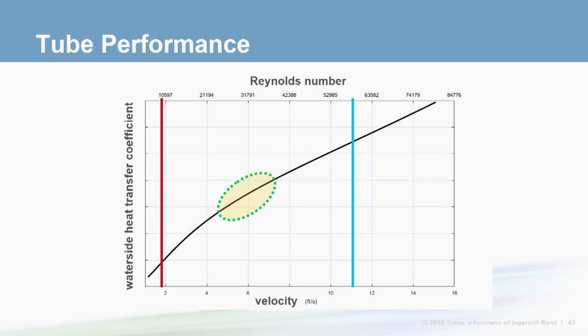And there is an additional concern for very low flow rates as well, and that is more targeted towards the condenser. The other concern has to do with tube fouling in an open condenser loop. As the flow becomes laminar, the potential for tube fouling, such as calcium buildup, increases. And the higher the tube fouling, the less effective the tube is at transferring the heat.